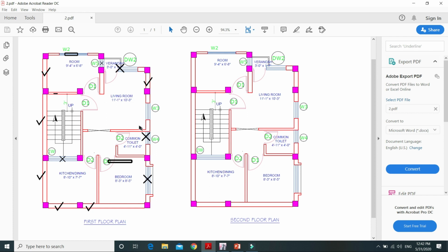You can see that some walls are not resting on the beams. For example, this is the partition wall which is not resting on a beam because there is not any grid. So the loads due to these partition walls are applied to the slab in this frame. We will know more about this later.